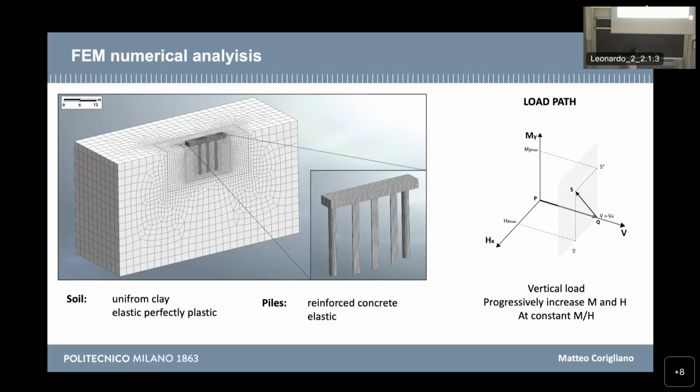The load path imposed to disrupt the verification is the imposition of a vertical load, and then after the imposition of a vertical load that represents the load induced by the weight of the superstructure, I progressively increase the bending moment and the horizontal force on the foundation. And this is representative of the seismic action in a pseudostatic way.